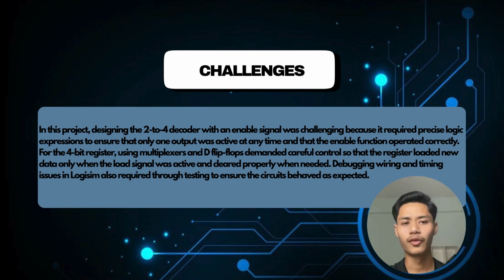For the 4-bit register, using multiplexers and D flip-flops demanded careful control so that the register loaded new data only when the load signal was active and cleared properly when needed. Debugging wiring and timing issues in LogiSim also required thorough testing to ensure the circuit behaved as expected.